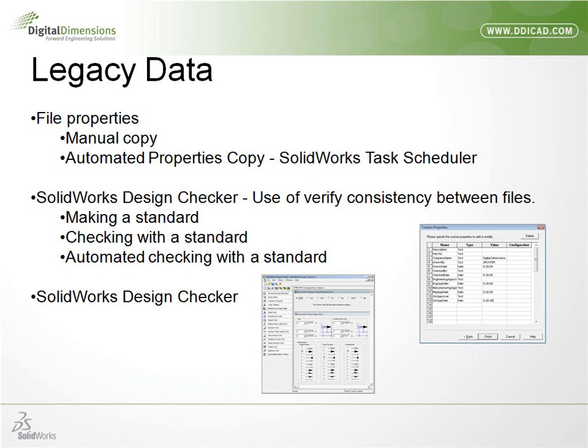Additionally, if everybody was using their own templates on their own workstation because you didn't know about file locations yet, the SOLIDWORKS Design Checker is the utility that will check the current drawing based on a known good template settings, and with that we could have it correct the drawing as you step through it. This can also be automated using the SOLIDWORKS task scheduler. So let me go over into SOLIDWORKS and show you this.